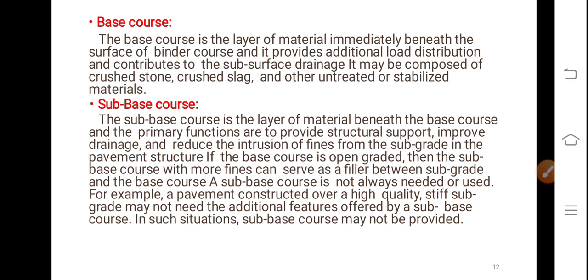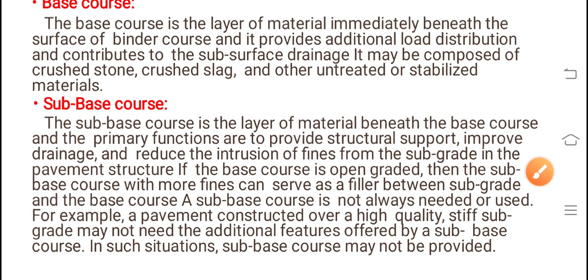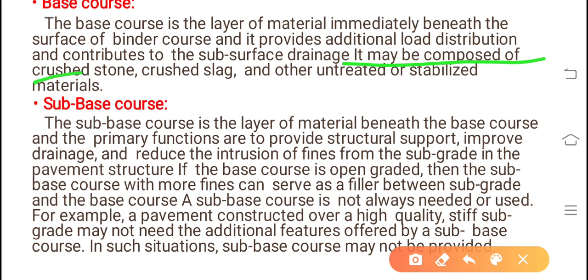Base course. The base course is the layer of material immediately beneath the surface or binder course, and it provides additional load distribution and contributes to the subsurface drainage. It may be composed of crushed stone, crushed slag, and other untreated or stabilized materials.